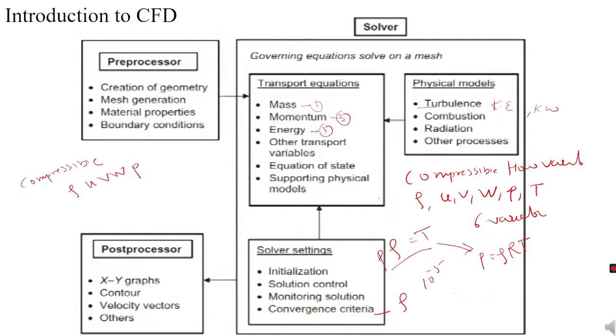So defining the solver parameters, as you know, initialization is very important. Proper, accurate initialization will help us reduce the simulation time or convergence time. Generally, for RANS models, steady state initialization has less impact, but it is critical for LES and DNS due to flow sensitivity.